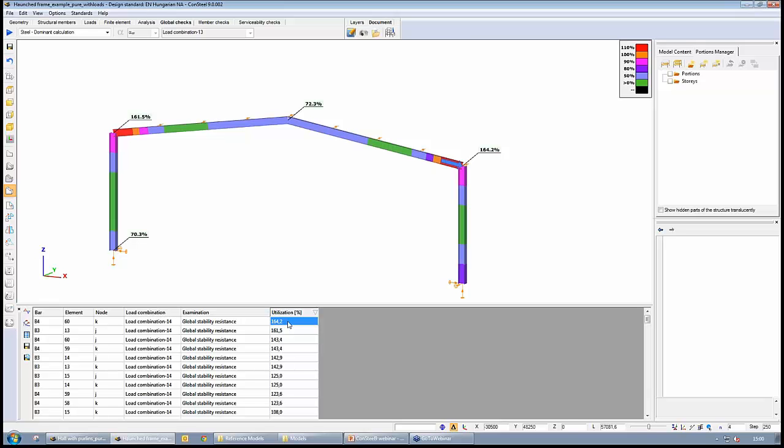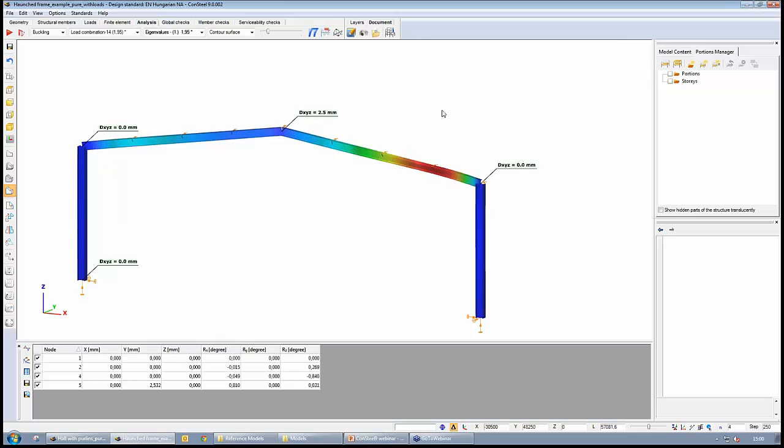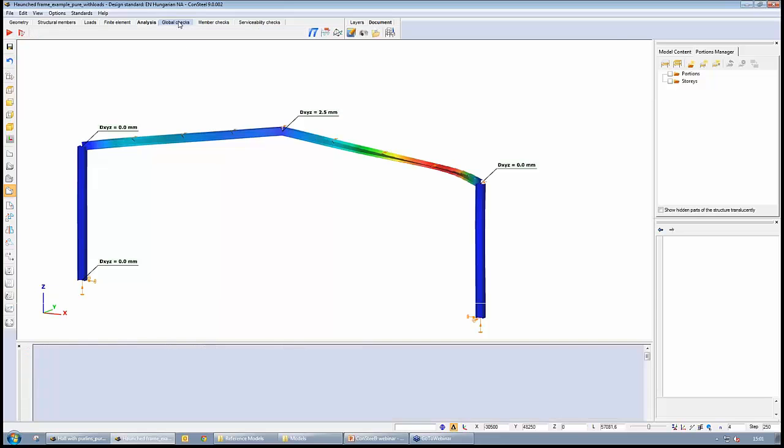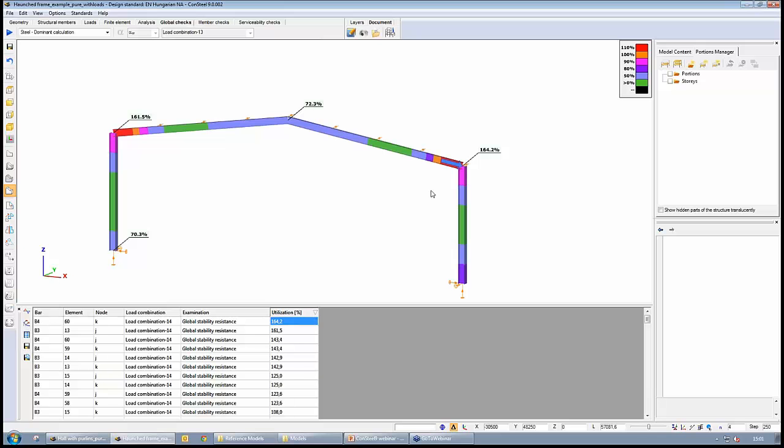So again, we can see that the difference in the position of lateral restraint makes a difference in the buckling mode and a difference in the connected elastic critical load level, and also a difference in the final check of this region based on the general method, because at the moment we will have a higher slenderness value.